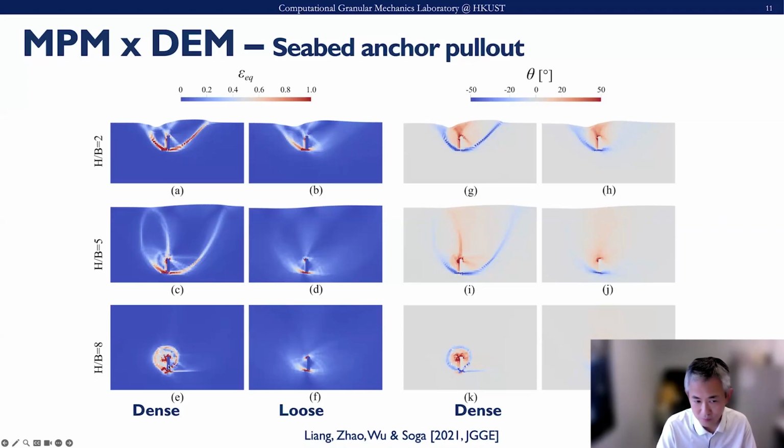Before the anchors, the sand will be pushed, but it won't really push to the top, because the bearing depth and the confinement are high. Then the sand will be pushed to the top and circulated over the top of this plate, and then fill the hole generated behind this anchor.